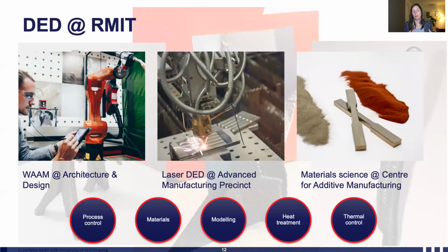One of the things we find with WAAM, as I've described, is that the characteristics of WAAM are not quite the same as welding. What we like to say about WAAM is, if you can weld it, you can WAAM it. If it's weldable, it's WAAMable. Well, actually, that's not entirely the case. In fact, what we have found is that some unweldable alloys will actually work quite well with WAAM. And really what we need to do as researchers is exploit the characteristics of WAAM and enable it to handle materials that you couldn't ordinarily weld.